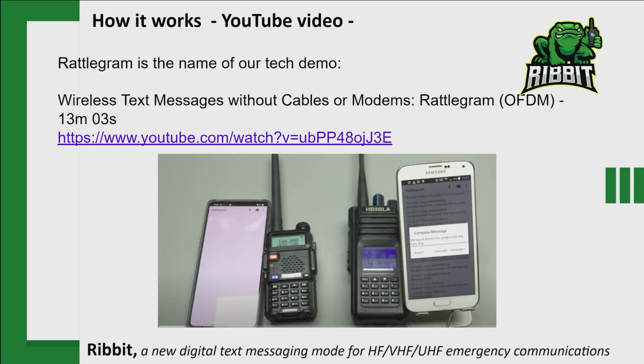Maybe this is piggybacking off the gentleman who asked about APIs. Do you foresee a time when you could send things beyond just text message? Because you could send any information, pictures or whatever. So when it comes to information density, text message is the sweet spot because currently we're able to send 170 bytes. In the new Ribbit, and I'll show that in the next slide soon, 256 bytes in 1 second. If you start sending images, you're going to have your transmission going on for minutes, and then you block the air and congest the air.